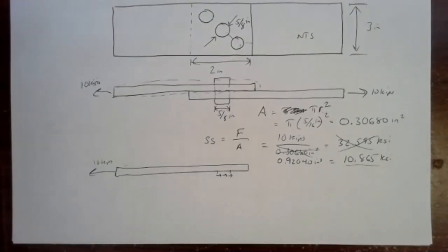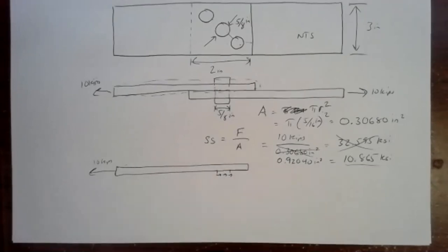So that's another important idea, and something that those of you who have been through sheet metal are more familiar with now, or at least understand why we did it the way we did it then. You don't want to just put one big rivet in the thing and have that hold it together. It's easier and more efficient to put lots of small rivets in. So that's another shear stress example.